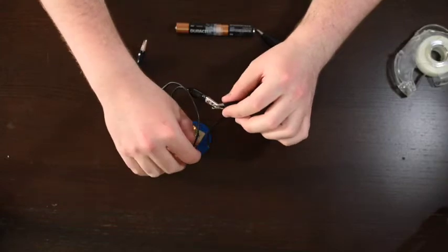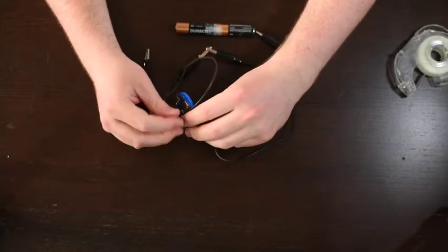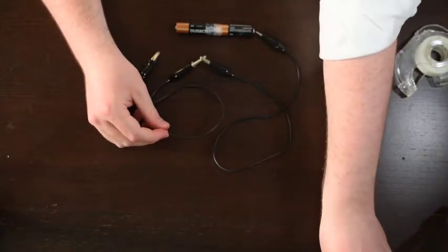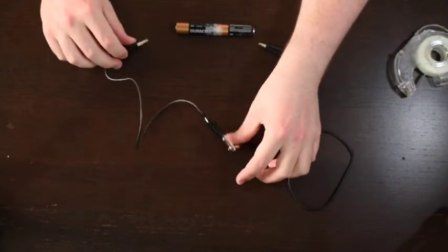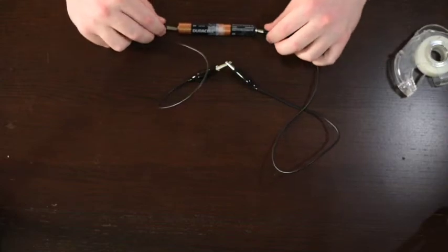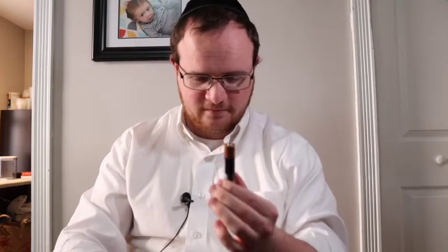That's if you remove the load, which I had taped down because it's easier that way. If you remove your load and you just have your battery and you attach it to itself, that's called a short circuit, and it's very dangerous. Do not do that, because it simply causes electricity to flow without anything lessening it, without anything using it, and that just generates heat. If you generate enough heat in one of these batteries, it can blow up. So, lesson of the day, do not make a short circuit.